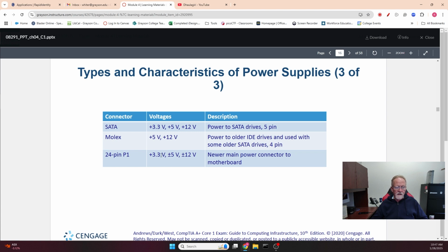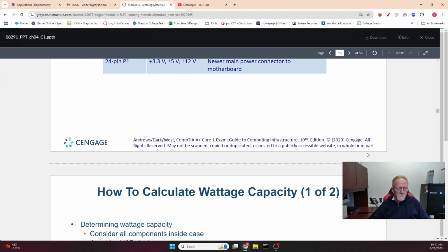So there are different positive and negative requirements, as well as different number of volt requirements. Polarity, that's what I'm looking for. There are different polarities required by the different components as well, because some things take a negative 12 volts, some things take a negative 5 volts. So you need to make sure that your power supply will provide all these different voltages.